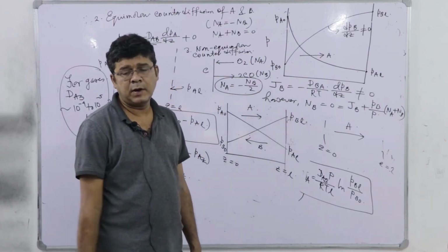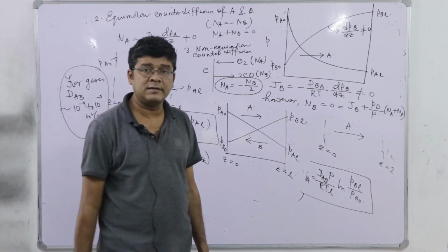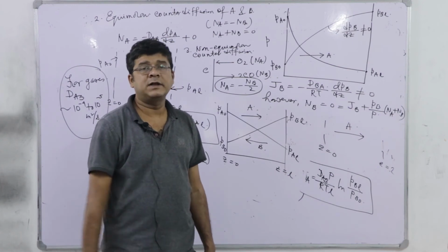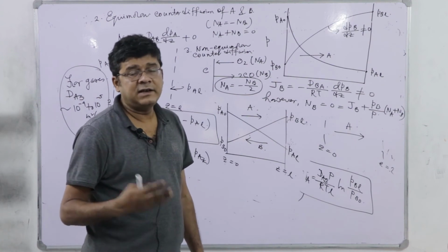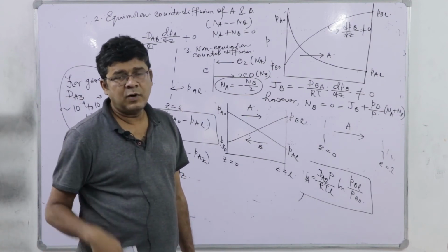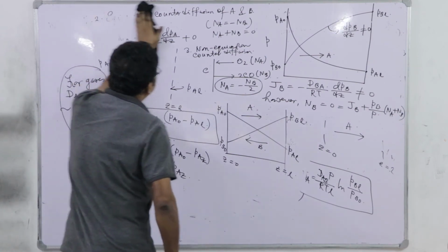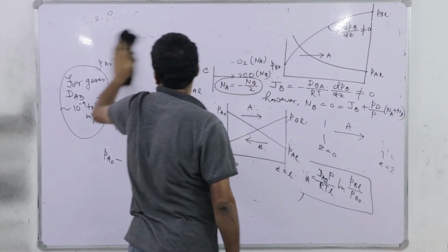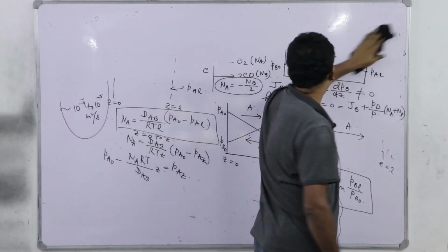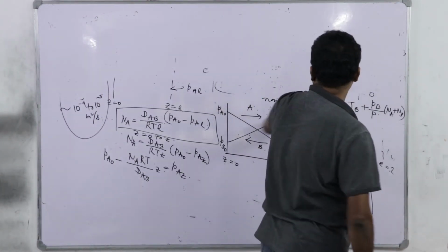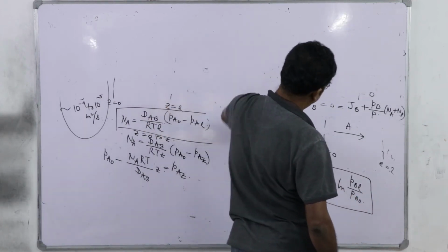It is not important from the perspective of conducting the experiment, but more importantly we have to understand the analytical scheme we follow here to measure the diffusivity, right. And this will be useful in solving other types of problems, how to incorporate the flux expressions of diffusion in overall mass balance.